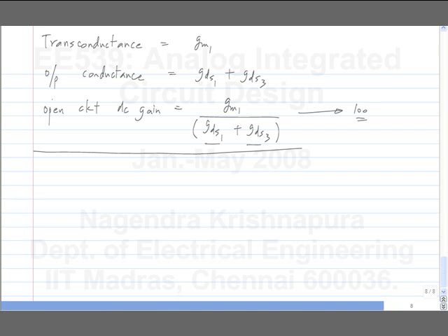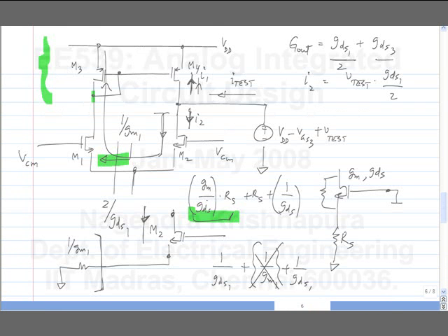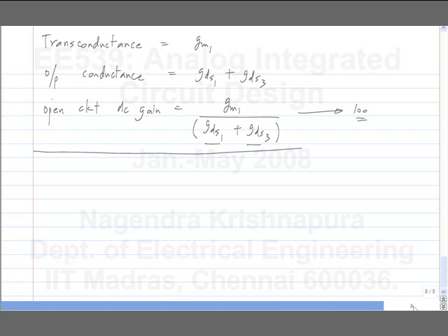The first method of increasing DC gain is to increase the length of all transistors. But if you are at a DC gain of 50 and you want to make it 5000, it's probably not going to happen by increasing the length of transistors, because you can't increase the length by such a huge factor. First of all, it will give you very large parasitics, and the device area will not be feasible. It will be too expensive.